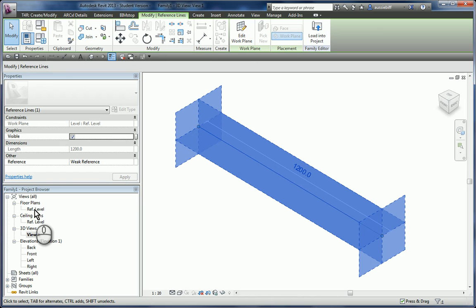Now, in order to build a family like this, you have to build a whole set of bones, and you do that using reference planes. And before you even make your extrusions out of wood for the flange and the web, you will have created a whole set of bone structure, and all guiding and all flexing themselves correctly.